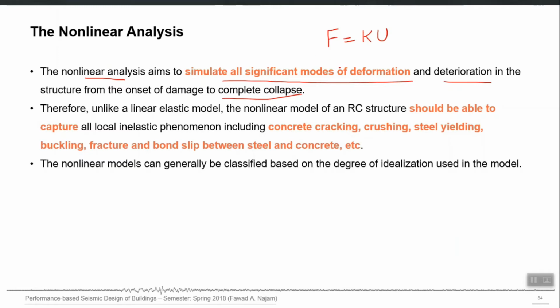So therefore a nonlinear model should be able to capture all local inelastic phenomena, for example concrete cracking, crushing, yielding, and also buckling, bond slip. All those are nonlinear phenomena, inelastic phenomena, right? And a nonlinear model should be able to capture them. There should be a feature in that model which takes care of these material deteriorations.